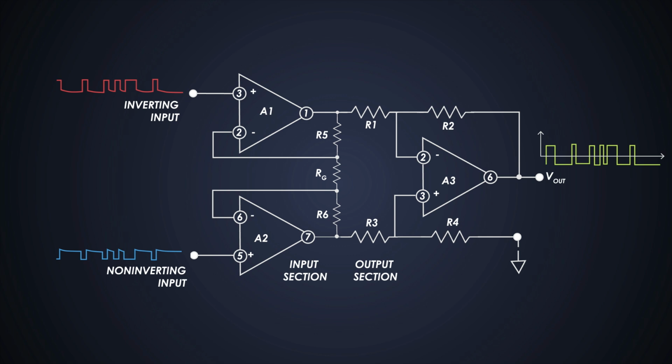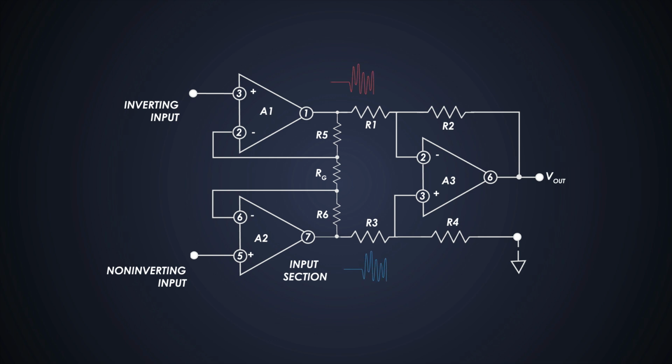This means that we may take as much gain as we want from this end by using RG without increasing the common mode gain and error. So the differential signal will be increased by gain, but the common mode error will not. So CMRR will increase drastically. Finally, because of the symmetry of this configuration, if there are any common mode errors by input amplifiers, the output difference amplifier will cancel it out. This is why it is superior in every way.